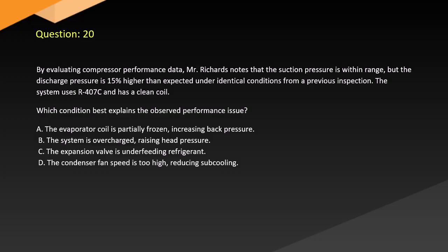A. The evaporator coil is partially frozen, increasing back pressure. B. The system is overcharged, raising head pressure. C. The expansion valve is underfeeding refrigerant. D. The condenser fan speed is too high, reducing subcooling.